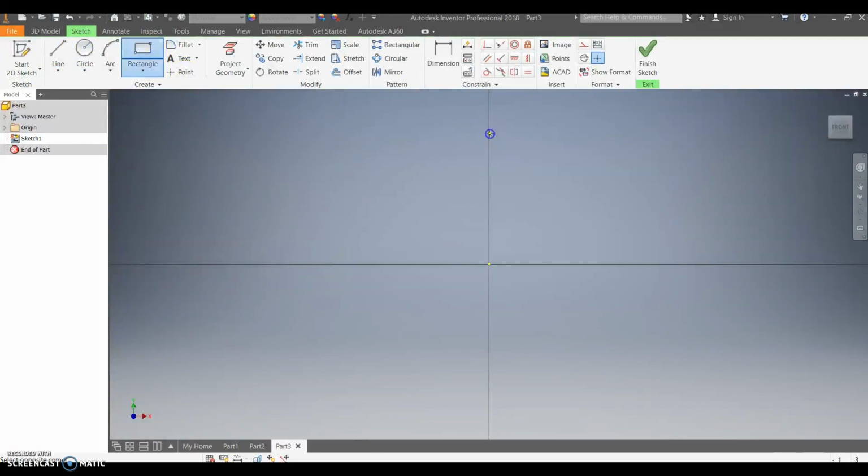So let's say I just drew a rectangle and I didn't add any dimensions. Okay. And then I drew another rectangle. I'm going to snap it automatically. See how it highlights that line? It's going to snap on there. I'm going to draw another rectangle. Square, sorry. It looks like it's a good shape, but we know there are no dimensions to this shape yet. Okay, but if you look, all of our constraints are there. Perpendicular, parallel, horizontal. I need to now dimension this part.